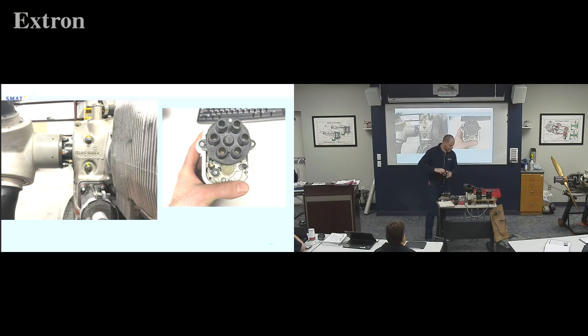That the gear goes between the magneto and the distributor block. Thought I had one set out. Here we are. So this distributor block sits on top of here, and there is one gear that is going to engage on the teeth on the magneto and engage on the teeth on here. If we only have one gear exchange, that means we're going to reverse the rotation once, right?